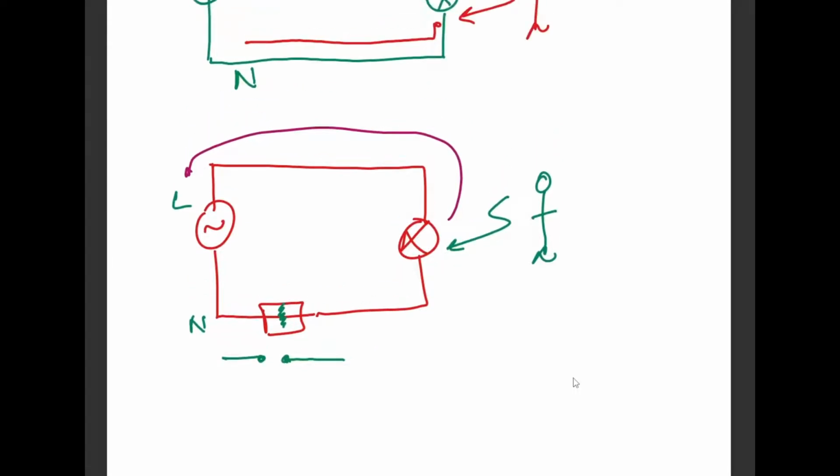Again, we are expecting that if the fuse has blown, if the fuse has melted, then it is safe to work on this machine. But if the person has installed the fuse in the wrong place, then whichever mechanic or operator comes close to repair the machine will not know whether the machine is actually off, or whether the fuse has actually cut them off from the live wire or not.